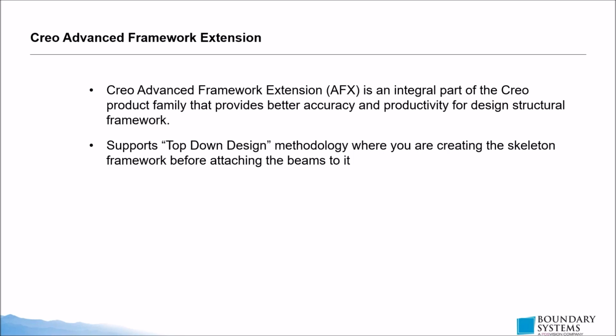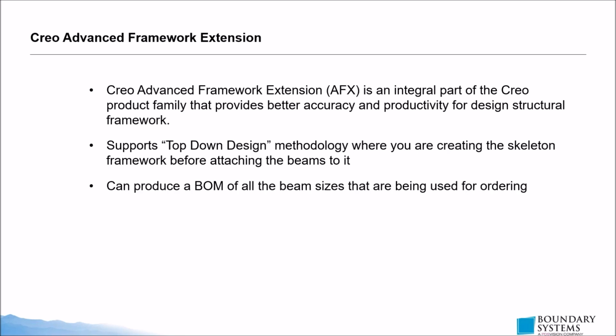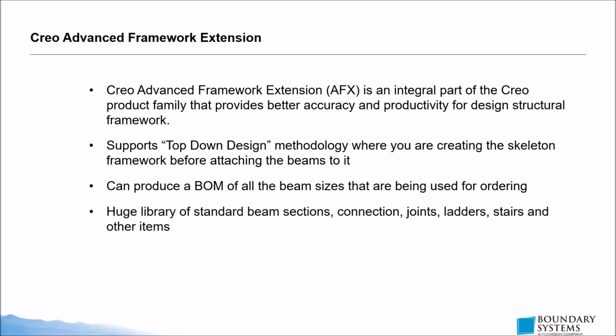It also allows you to create the sketches on the fly if you don't have the actual framework there, but you can create it up front and then simply select the curves to attach the beams to. With that, you can produce a BOM with all the beam sizes that are being used, for ordering. So once we create that structure, we can create a BOM that tells us all the different sizes. We'll see that in the demonstration as well. The software also comes with some standard tables that you can use to produce that information.